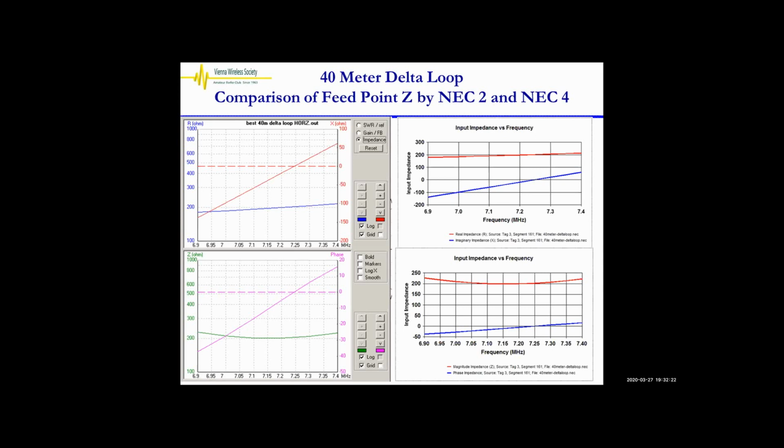And what I do with the antenna is I put a 4-1 balun at my feed point. So it has a very broad band. So this 200 ohms you can see here transforms down, divided by 4, and I have a very nice broadband response of my delta loop. And I came up with the optimum dimensions using the modeling tool. Okay.